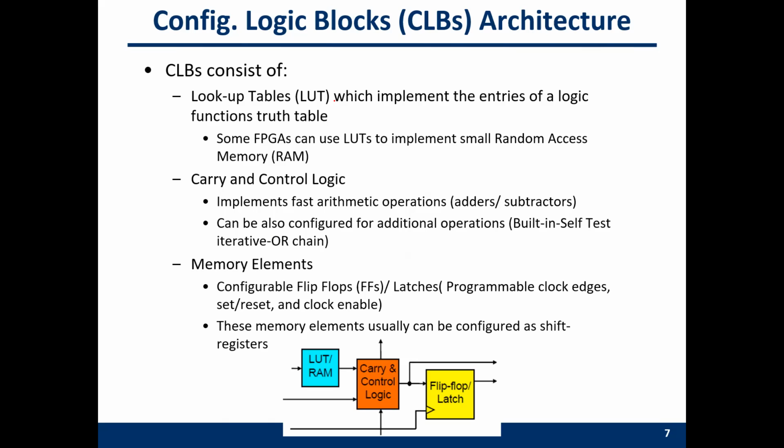Or you can use them to serve as some circuit for the testing. You implement something in the lookup tables and you need to do some testing on that. You can also utilize these carry and control logics. Of course, we have a memory element, the latches, to support the finite state machine, to support the multiple clock operation.